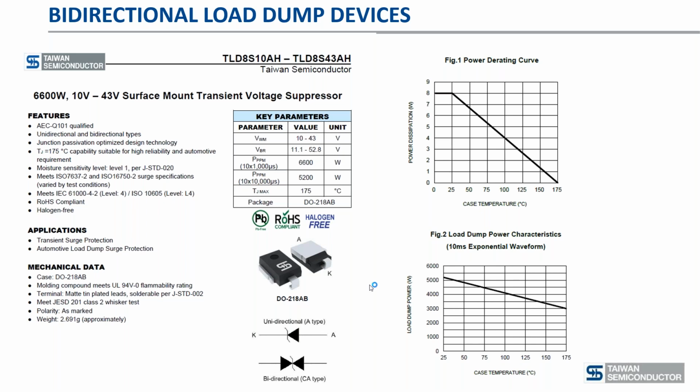So that also gives you an idea. Of course, if you do 3 kilowatts at 175 degrees C, of course, the junction temperature is going to be exceeded here. So both graphs here, the single pulse graph and the steady state graph, are in this data sheet. That happens rarely, but we're doing it in this device here.